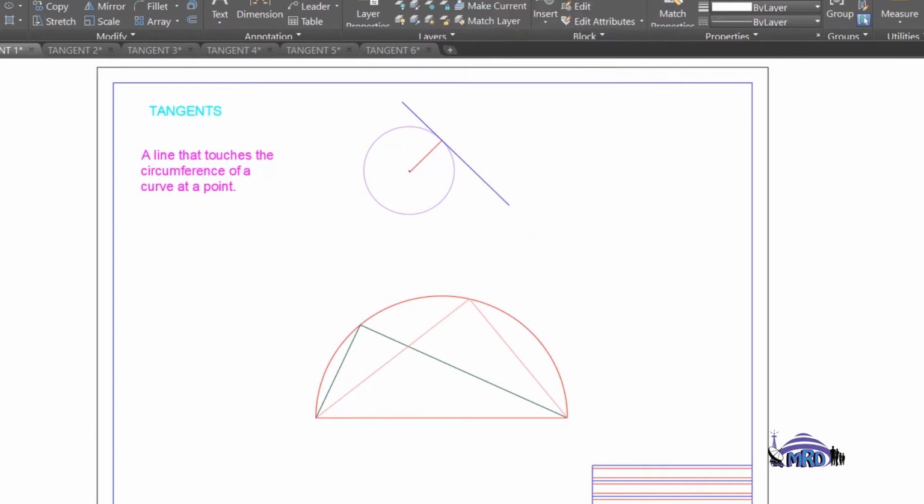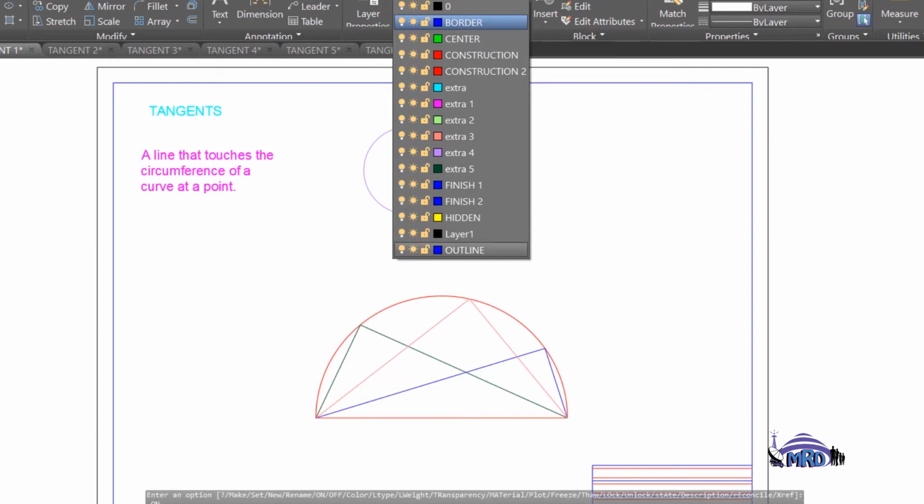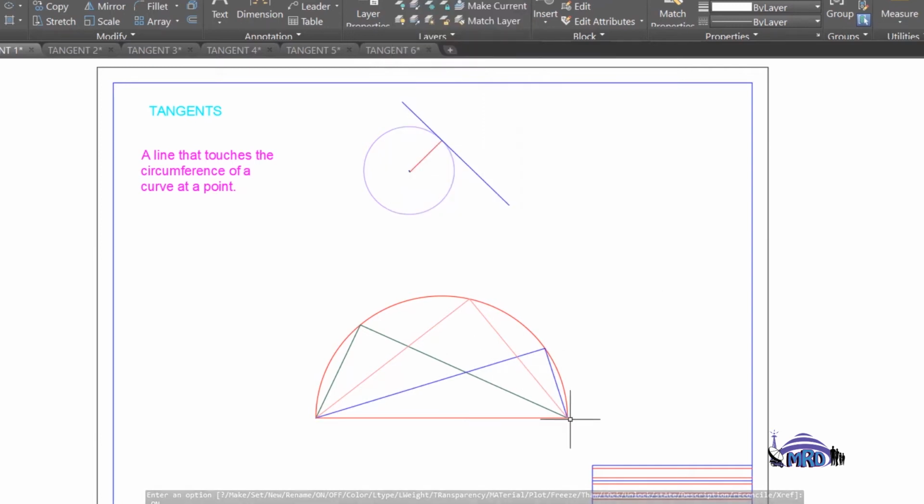But it is critical to note this, and I'll just throw in another one just to make sure that we are on the same page, just from another position. So this just confirms for you that no matter where on the circumference of this curve you select a point and you make the connections, that the angle formed in here will always be 90-degree angles. And this principle is the principle which works for the construction of tangents. So you will see as we work that once we produce tangents, we are also on most of the constructions applying a principle similar to this.